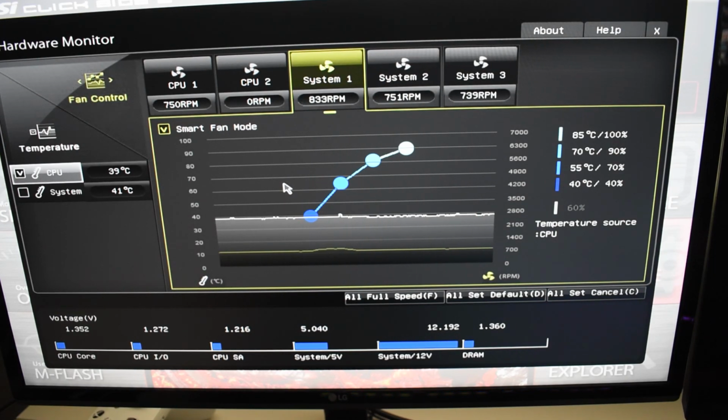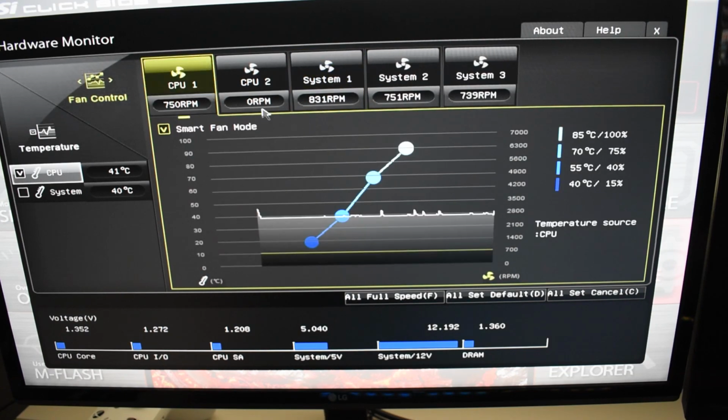If you want the fan to turn on at 0 RPMs, then sure, you can, but please be wary that if you do, make sure that they come on at least a little bit up here, so that if it does develop some heat, it can cool. Unless your PC is set up to be passively cooled, it's definitely not. And for a CPU fan, do not do that, just because the CPU is always making heat.